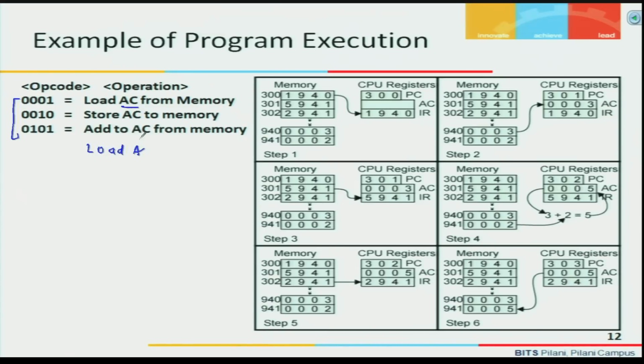So here the source is given that, okay, from this memory location A data has to be read, but the destination is not given. So the destination is implied here. If you are reading from the memory, your destination is always fixed, that is the accumulator register. So no need to specify it in the instruction, it will save the number of bits in your instruction. So it's implied that whatever you are loading from the memory will go to the accumulator register. This is always fixed, it is hard binded in your hardware.